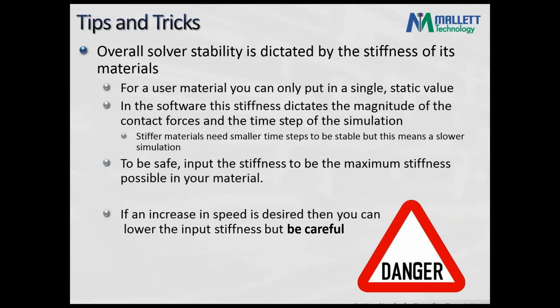This stiffness dictates the magnitude of the contact forces. A stiffer material generates higher contact forces when it bumps into something else, and it also dictates the time step of the simulation. If you can imagine a stiffer material, it'll vibrate faster, and in order to transmit that information from one element to another, your time step will need to be smaller